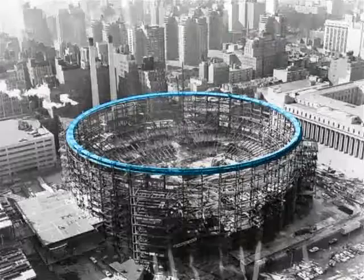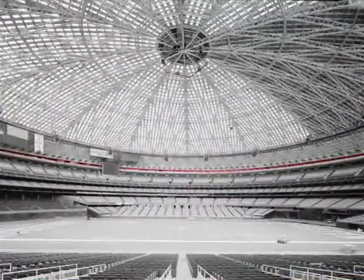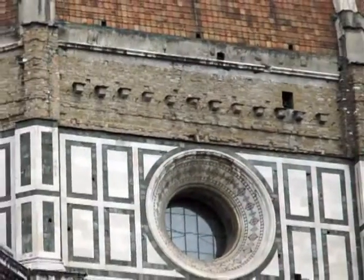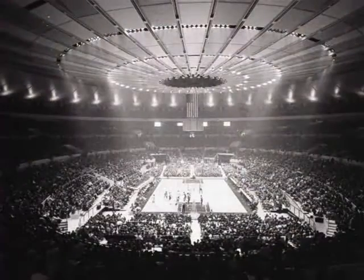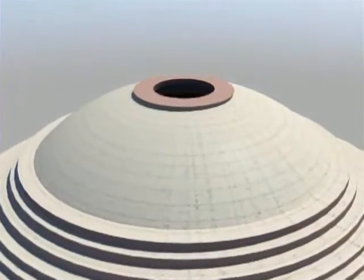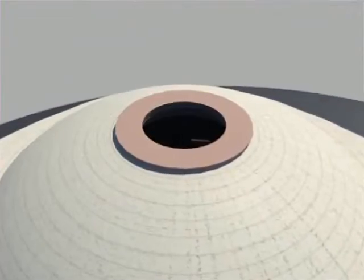Second, the lateral restraint around the base of the hanging dish is a compression ring. The lateral restraint around the base of a dome is usually provided with a tension ring. Remember Filippo Brunelleschi's chains around the base of his dome in Florence. And finally, that central element in the middle of the hanging dish is a tension ring, while a dome uses a compression ring in the center. Remember the oculus of the Pantheon.